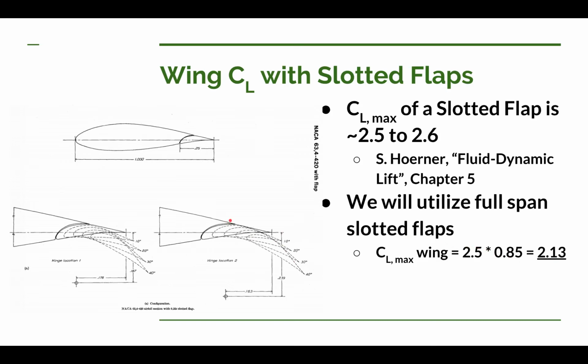Let's get into a couple of the other advantages and disadvantages of these slotted flaps, at least compared to plane flaps. One possible advantage is that if you do a good job of fabricating your slotted flap and your wing, you can actually seal this slot in here so you don't have air traveling from the high pressure underneath to the low pressure up above.